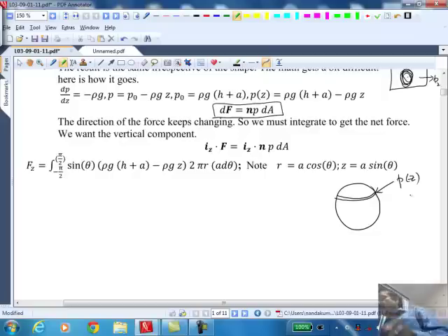Okay? So, does anybody have a question on this equation? I'm talking about that equation. How do you come up with that? Because these are translations of conceptual ideas into mathematical language so that we can process it further to get the answer. So what conceptual idea does it translate? That the differential force is the pressure times the differential area, because pressure is force per unit area. So if I multiply by the area on which it acts, I get the net force that acts on this ring that I have indicated here.